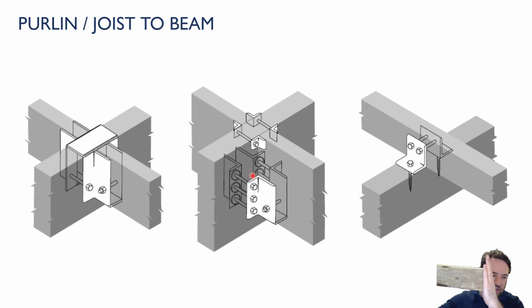Why? Because if I put some bolts here, and I'm just bearing on these two bolts, for example, and I'm pressing this down, I'm basically loading this beam in tension perpendicular. I'm trying to split it apart, right? Like if I have a bolt here and I push down on it at the end, I'm trying to pull those fibers apart, which we know for wood is not a good way to do it.